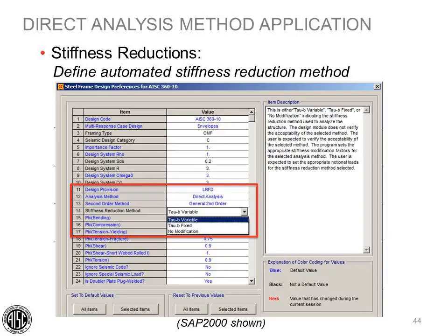For instance, SAP will not reduce the stiffness until after the member design checks have been performed. So you'll need to run the analysis, perform a design check of the members, then rerun the analysis so SAP can calculate the proper stiffness reductions, and then redo the design check again. Then if you change member sizes, you'll need to redo that cycle of running the analysis, performing a design check, then rerunning the analysis so SAP can calculate the correct stiffness reductions, and then perform the final design check again.